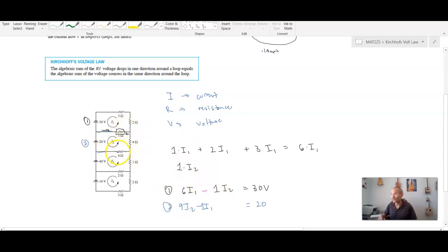And then also this resistor here, right? This resistor here is receiving current from I3, and so the voltage drop because of this third loop is going to be 4I3, but that's going to be negative, since, once again, I3 is flowing in the opposite direction as I2. So you can see the negative terms: here we only have 1 because there's only a loop below loop number 1, but for the second loop, we have to consider the current from the first loop and the current in the third loop. Okay, let's see if we can get the hang of this.